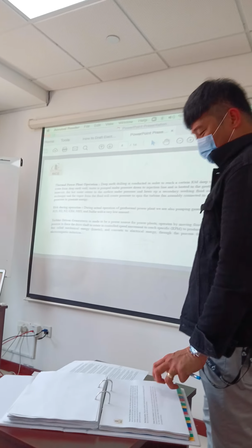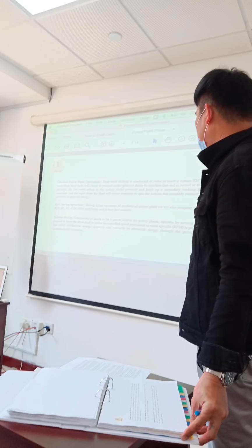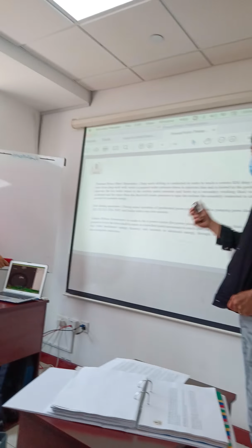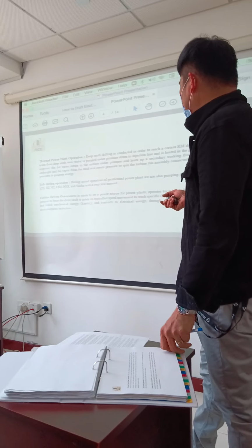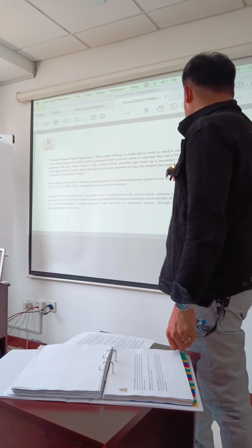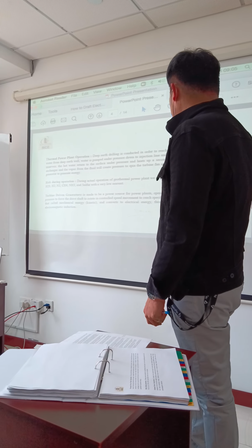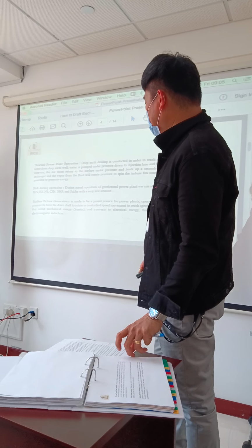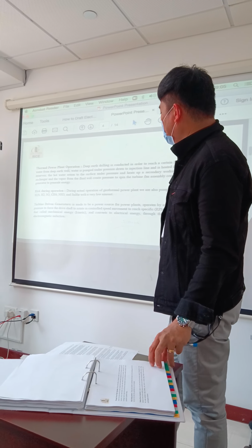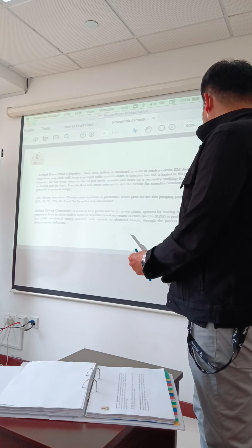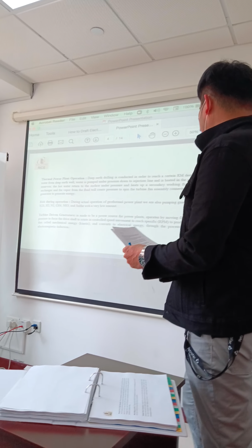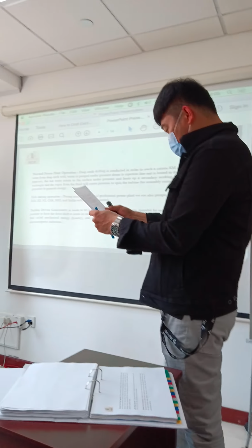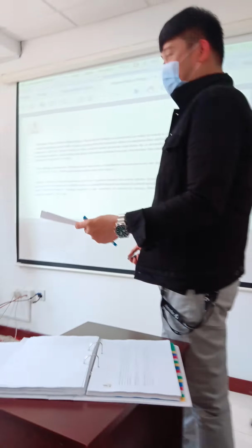Risk during operation. Of course, we are pumping water and it involves air. If we pump water under pressure, we will also get small amounts of these chemicals: CO2, H2S, H2, N2, CH4, and NH3. The most dangerous chemical there is the H2S, because the H2S can kill anyone within seconds.